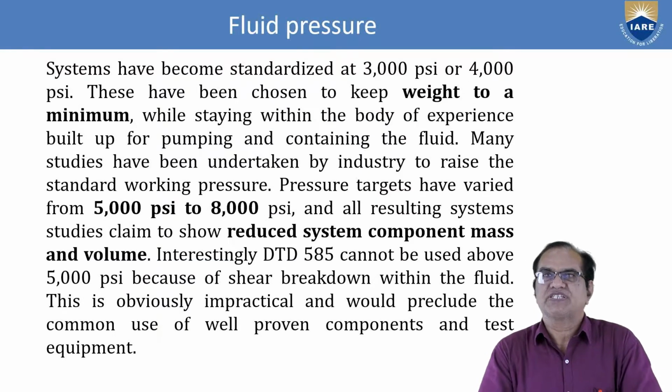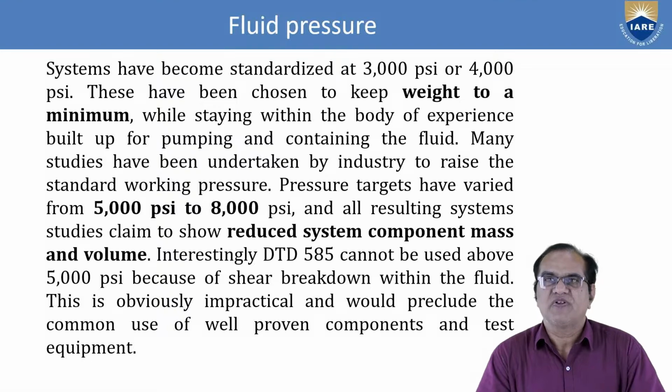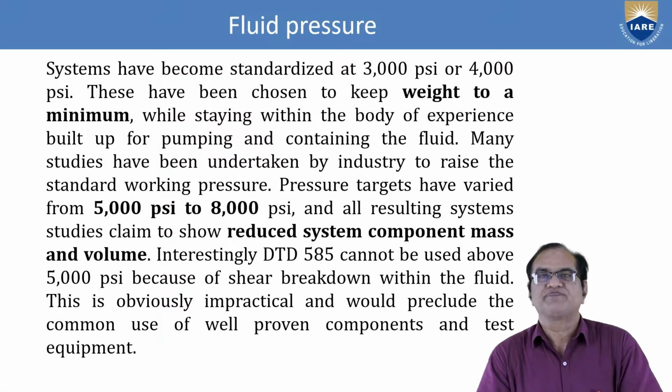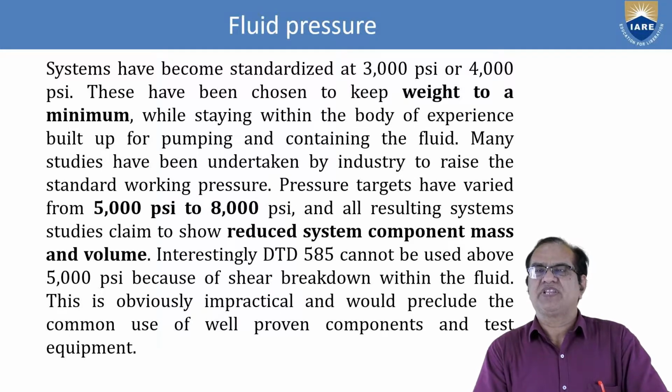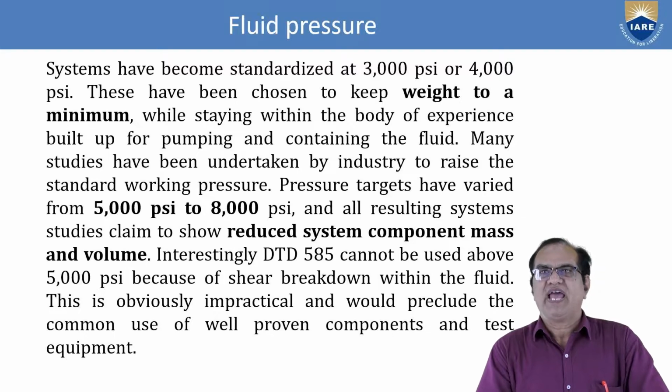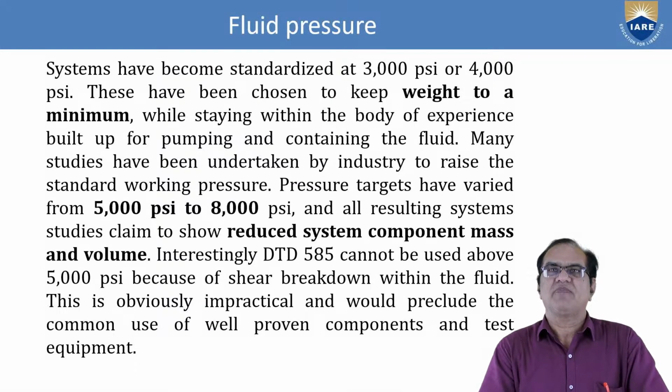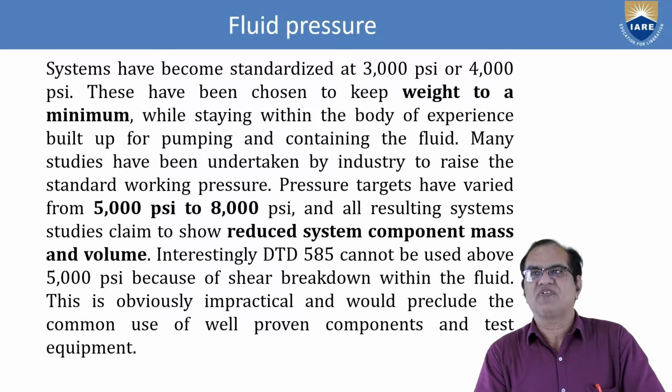Next, I am going to discuss the properties of the fluid. Fluid pressure: systems have become standardized at 3000 psi or 4000 psi. These were chosen to keep weight to a minimum while staying within the body of experience built up for pumping and containing the fluid.